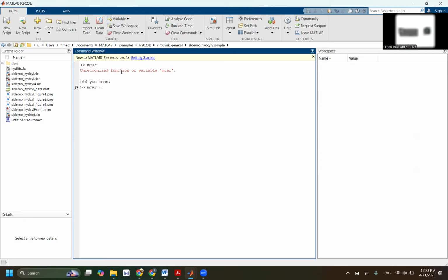What do you think the mass of the car? The reasonable amount of the mass of the car? 2,000 kilograms, say. But remember, this is just 1/4 of the mass of the car. That's why this is called quarter car model, because you only take one wheel, one suspension, so you don't take the mass of the whole car. So roughly take quarter, so 500.